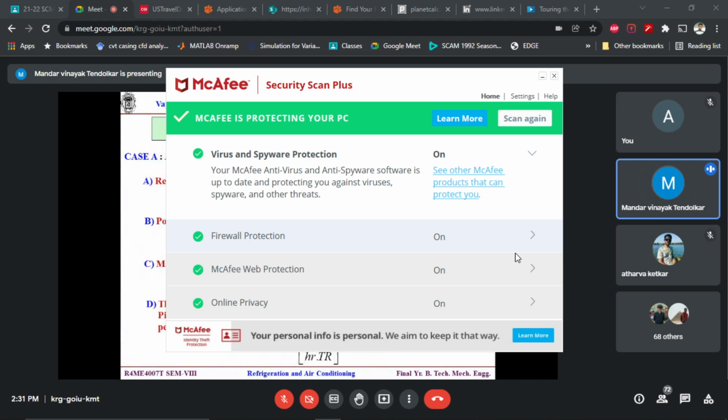Fine, this is my dry compression cycle. So refrigeration effect, H1 minus H4. Both values known to you. Power consumption of the compressor, H2 minus H1, both values known to you. Then mass flow rate. Now the refrigeration effect is known. You substitute in any of the units. I have taken 211, that is kJ per minute. You can use 3.5167, that is kJ per second, or 12,660, that is kJ per hour. So based on that, your mass flow rate will be kg per minute, kg per second, or kg per hour.